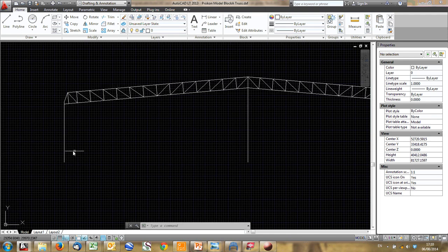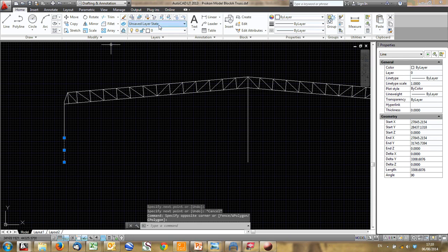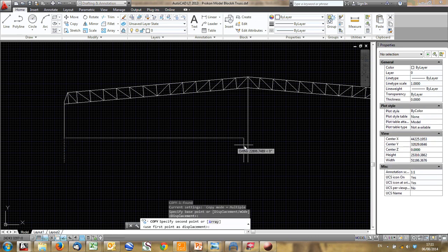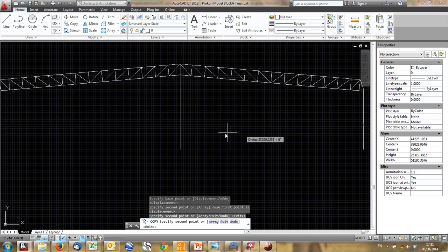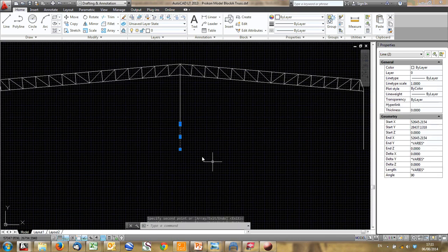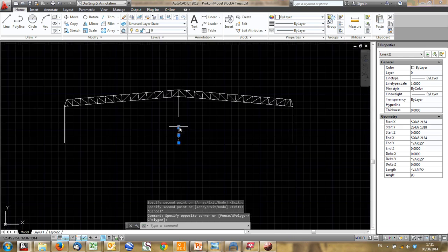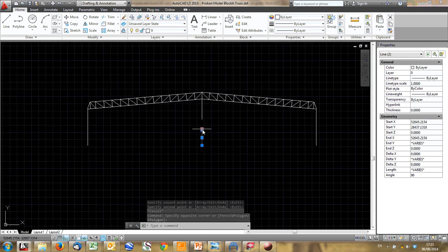So it's useful to purge your drawing. Also, make sure wherever you need a node, let's say we've got our concrete column there, you have different lines wherever you need a node. So we'll add sections like that. They don't necessarily have to be different colors. Add it all the way along, so at least then you have a line stopping there, so you know it will create a node when this is imported into Procon.